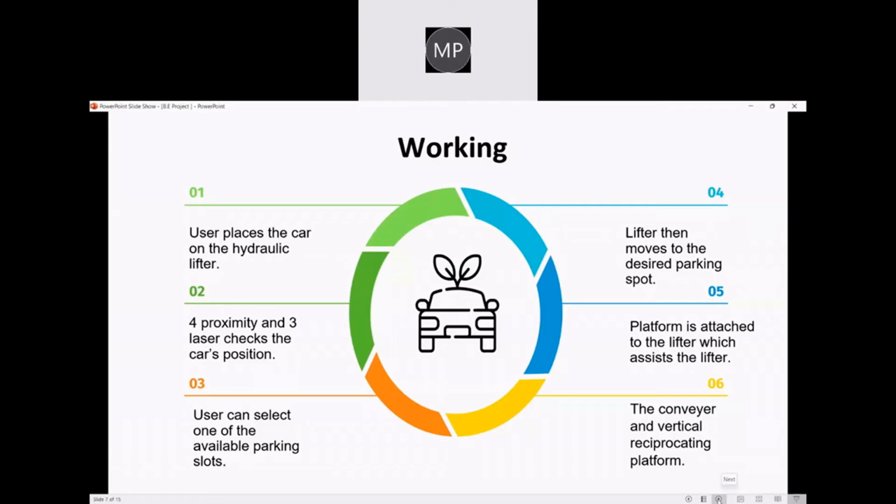Once the car is on the intended floor, a control system tells the electric motor to slowly shut off the pump. As no more fluid is flowing into the cylinder, the oil that's already inside the cylinder is trapped there, which means that the piston rests on the oil and the car is held motionless.